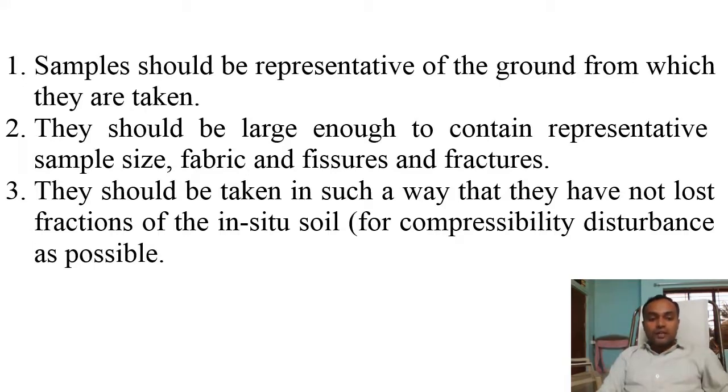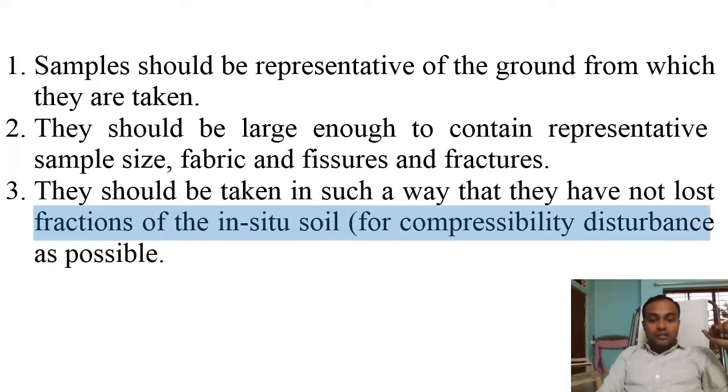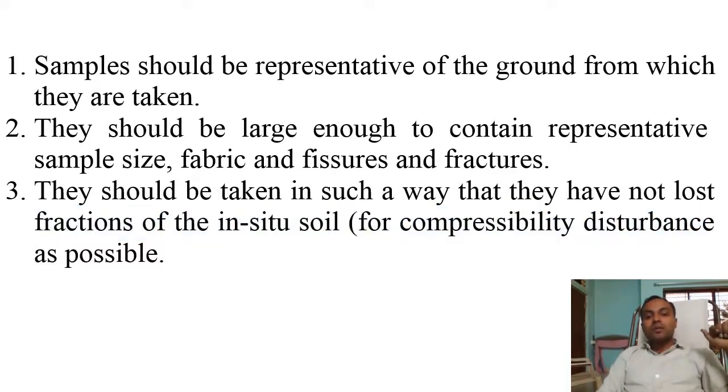And the third point is that they should be taken in such a way that they have not lost fractions of the in situ soils, with compressibility and disturbance as little as possible. Whenever you are collecting the soil sample, the third point says that as much as possible, you should not disturb the soil sample.